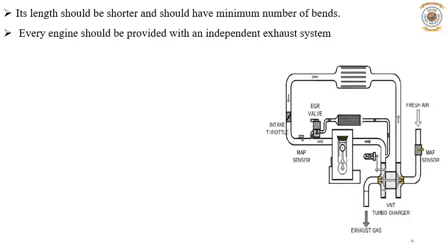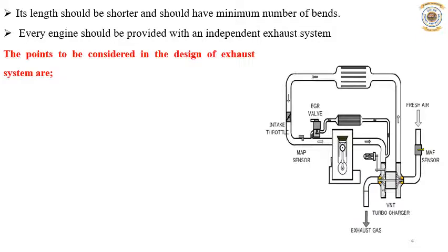And we can use that heat for preheating the air. Here fresh air is coming, and it gets heated up by the waste heat, and then it goes to the engine, so that we can improve the power output.